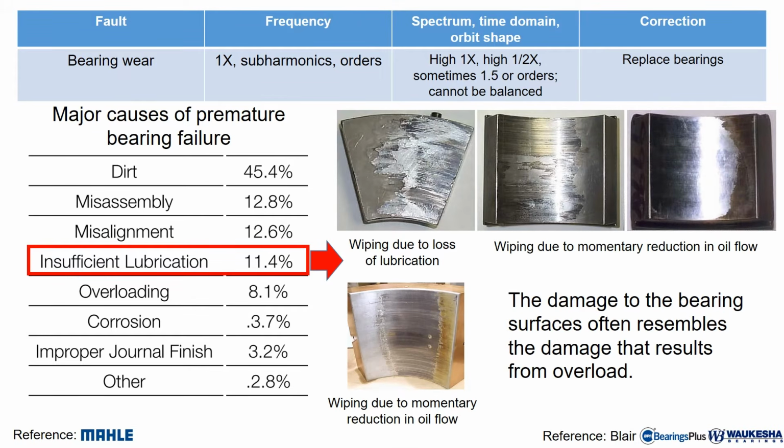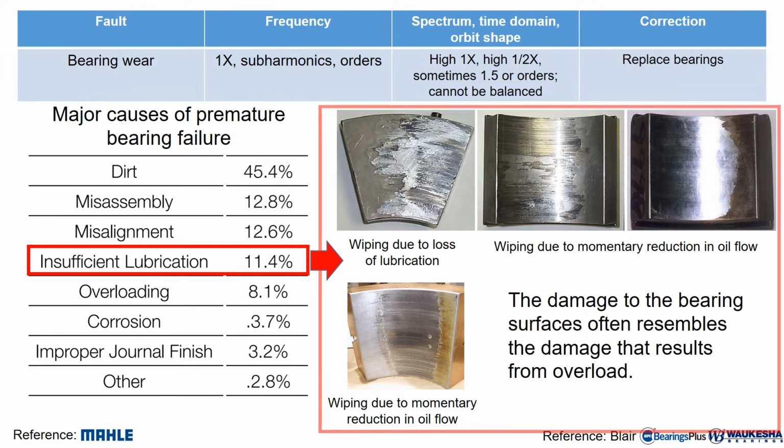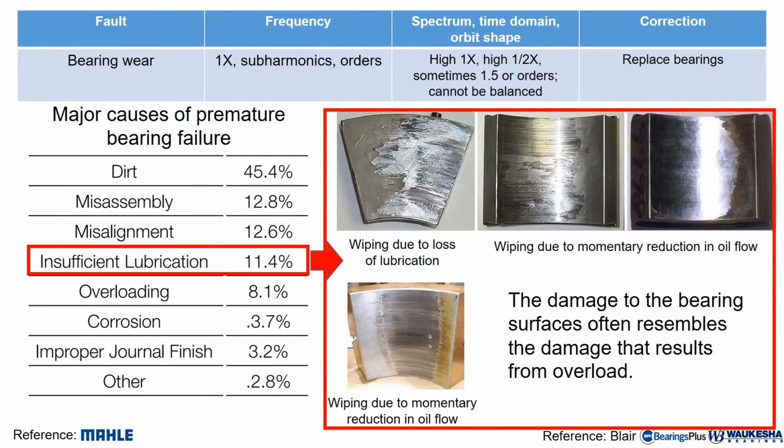Let's look into bearing wear due to insufficient lubrication. The damage to the bearing surface often resembles the damage that results from overload. The surfaces can be wiped and the babbitts smeared.